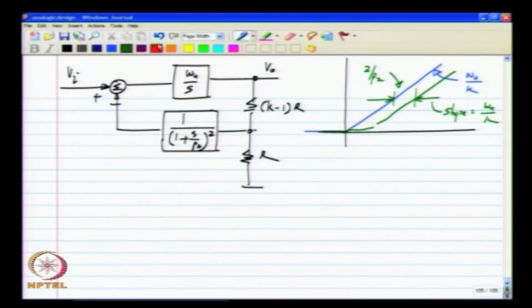So, this is the unit step response of the loop gain, and it again acts as a delay. So, for this particular case we will try to solve for the condition when there will be sustained oscillation, just to see what happens when we go to higher and higher order systems.